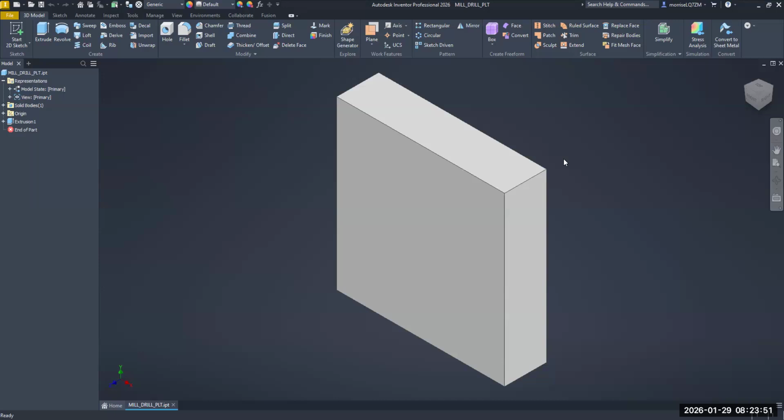All right, so drawing a block is not too hard. Now, the next thing we want to do is put a border going around this, because the tool that we're going to use is a 1/4 inch diameter tool, but we're only going to take off 1/8 of an inch all the way around this block. Let me show you how to do that. We're going to take 1/8 of an inch off all the way around the perimeter of the block with our tool.